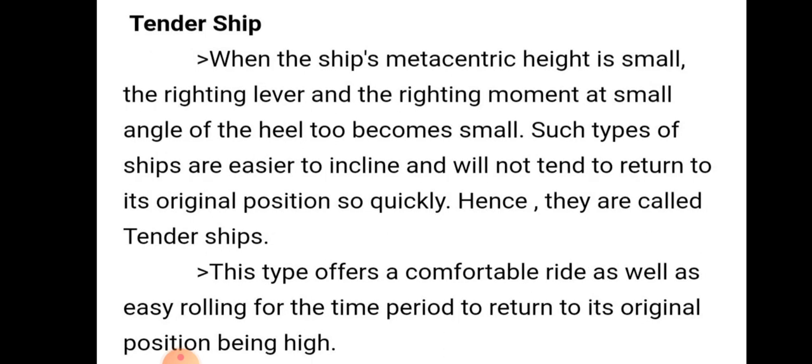Tender ship. When a ship's metacentric height is small, the righting lever and righting moment at a small angle of heel also become small. Such ships are easier to incline and will not tend to return to their original position so quickly. These are known as tender ships.